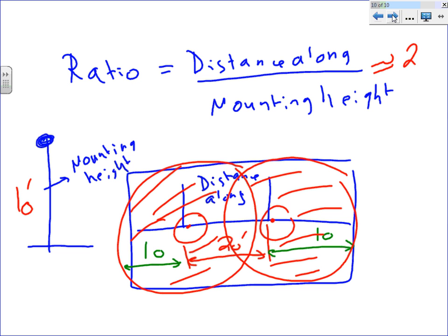Why is it important? Because if you're working on this equipment, guys, not only do you need to be able to walk around the equipment, you need to be able to push the buttons and read these things. So there are a lot of applications where you have to do calculations on the wall, not on the floor. They call it vertical foot-candle. There's a couple of formulas. I will do it, not today. How to calculate it: it's the same formula, but they use the sine instead of the cosine, so the light shoots onto the wall.